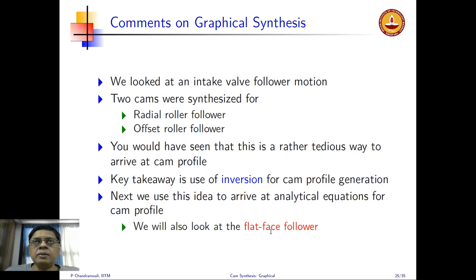Now, of course, we have not done a flat face follower. Knife edge we are not going to do, because that is something that we rarely use because it creates wear and tear on the cam. When we do the analytical equations, which is what the next set of lectures are going to be, we will look at the flat face follower at that point of time. We have not done it graphically. I have limited myself to a roller follower, both radial and offset, and we have left it at that.